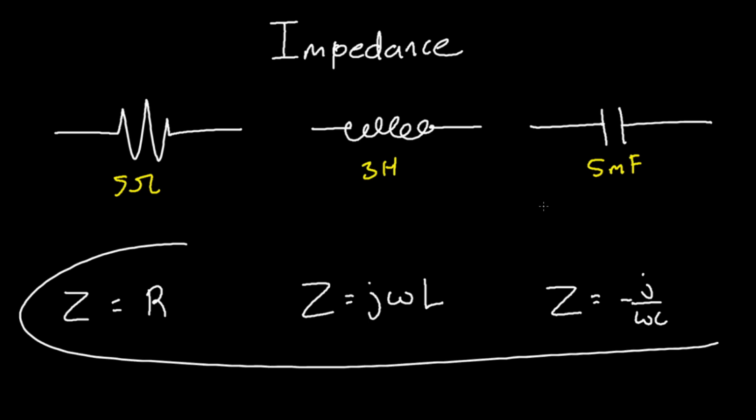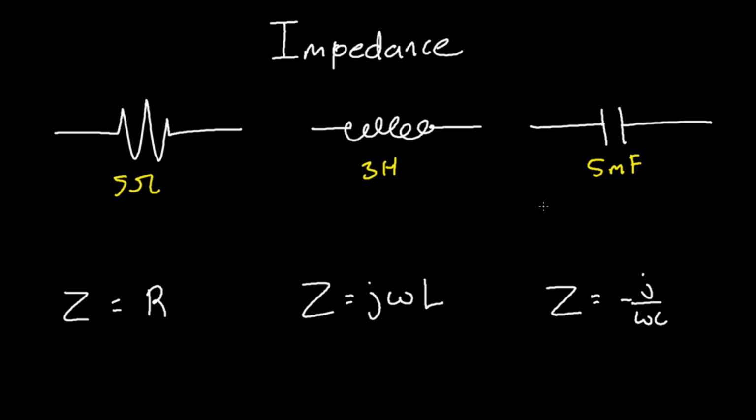And the thing about all these impedances is that you can treat them just as ohms. The unit for your impedance you could just simply treat as ohms. And what can you do with ohms? Well, with ohms, you can have resistors in parallel, or resistors in series too. So let's go ahead and look at this circuit here, with some other circuits to the left and right. We can actually combine all of these into one singular resistor, quote unquote.